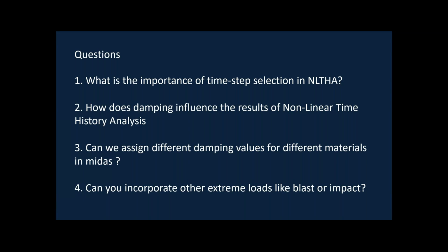Generally, 1/10 of this particular time interval of the record is considered, that is 0.001 or 0.005. So the minimum of 1/10 of the interval or 0.005 seconds is considered as the time step in the case of nonlinear time history analysis.